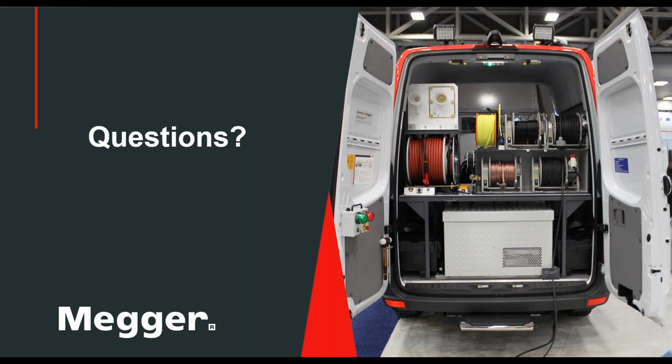Now, there are some tests you can do when you don't use high voltage, when you just use low voltage signals. For instance, if you just use a TDR, you can have a motor connected, but the motor must be de-energized, obviously, right? That way you can see, because the motor windings will show you on a TDR an open circuit, okay? So it is possible, but the basic rule is any high voltage testing or fault locating, you must be disconnected on both sides of the circuit, and on the near end, you typically connect your equipment.